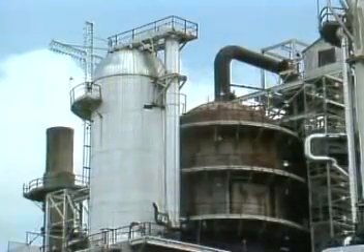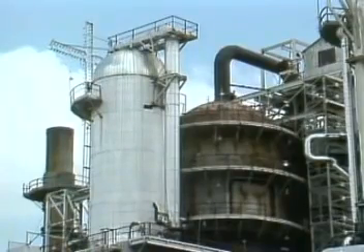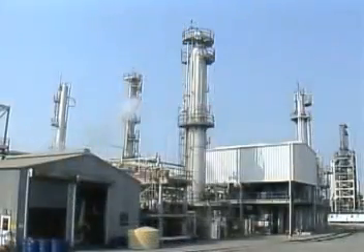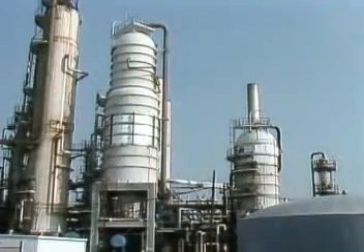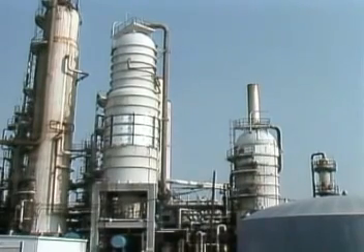Higher rates of vapor loading generally require a larger diameter tower. Lower rates of vapor loading can be handled in a tower with a smaller diameter. Some distillation towers operate at a low pressure. In these towers, a tremendous volume of vapors may be produced, so the diameter of the tower must be large to handle the vapor volume. Since a lower volume of vapors will be produced in a distillation tower that operates at a high pressure, the diameter of the tower can be relatively small.